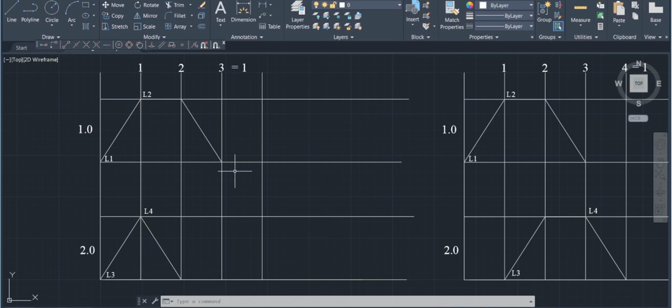Okay, so the last limit switch that will be pressed in order to repeat the sequence is L1. So L1 will be the last one, so we will use this L1 in order to recycle the cylinders.